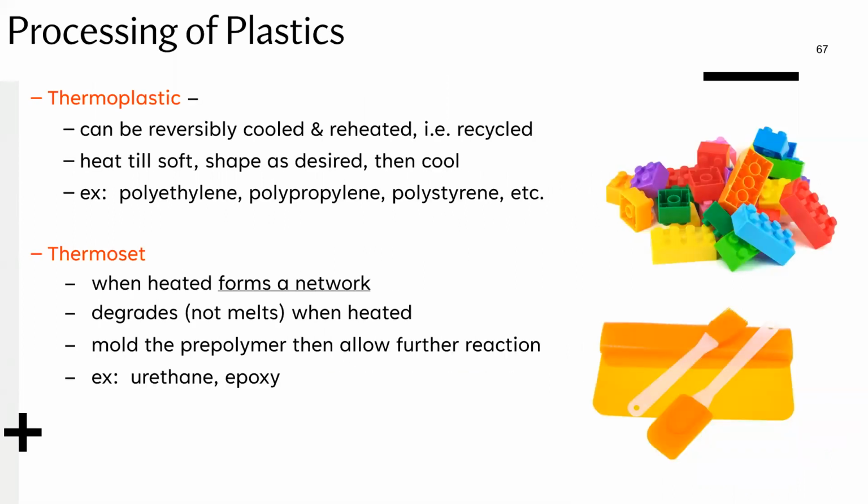So in general, you know that polymers are divided into two main groups, thermoplastics and thermosets. What's different is that, as we've mentioned multiple times, thermoplastics, as the name suggests, are plastic at elevated temperatures, so you can heat them up and reshape, cool them down and maintain that shape. Examples of these are polyethylene, polypropylene, polystyrene. These are the materials that we previously explained.